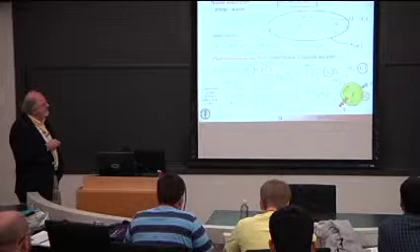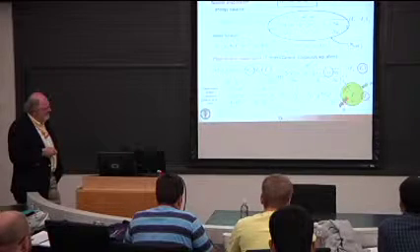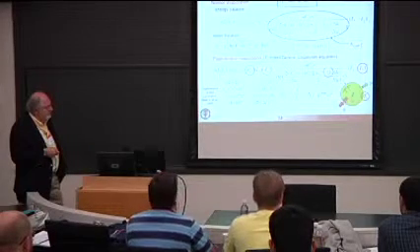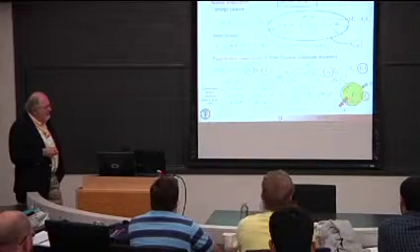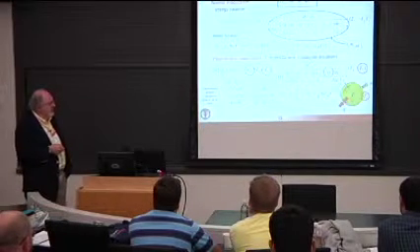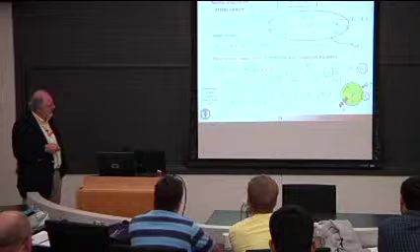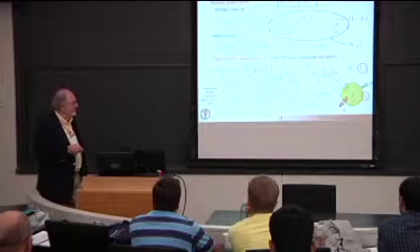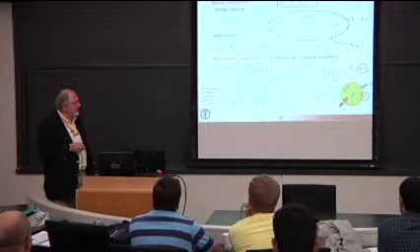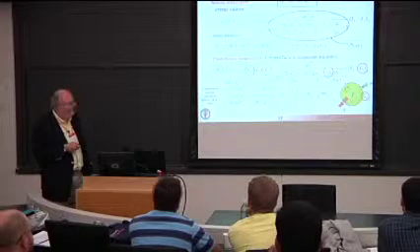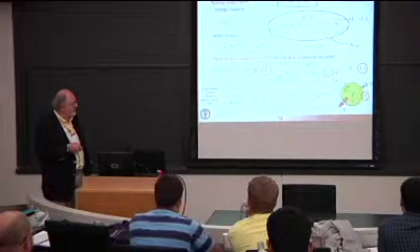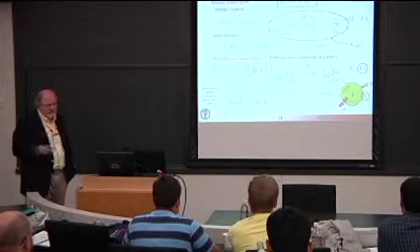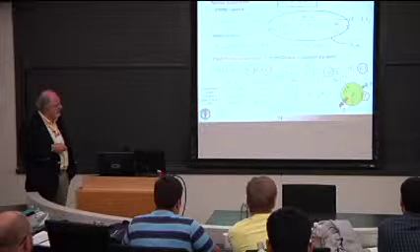We need a heat transfer coefficient, h here. h is determined knowing the conductivity of the droplet material and a boundary layer thickness, this thickness here, which determines essentially the gradient of temperature in the vicinity of the surface. How do we get that boundary layer thickness? A lot of people have done work, for example, Bill Sirignano's group, that have shown that essentially this boundary layer thickness grows as the square root of time. It's a diffusion problem with some sort of effective diffusivity. And that effective diffusivity depends on the Reynolds number of the drop and so on. So that's included in this analysis.